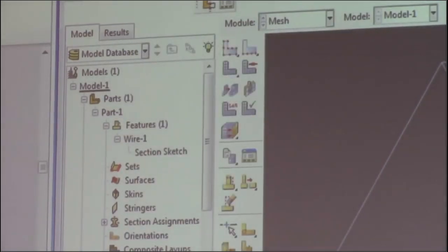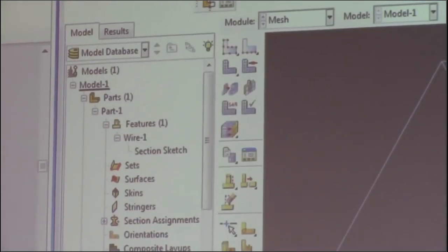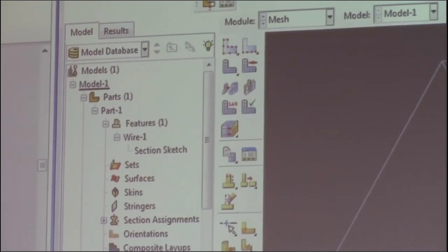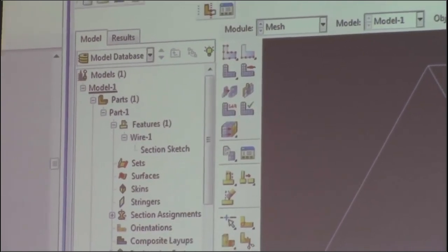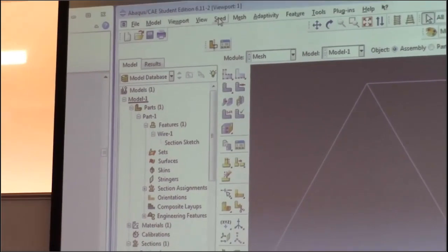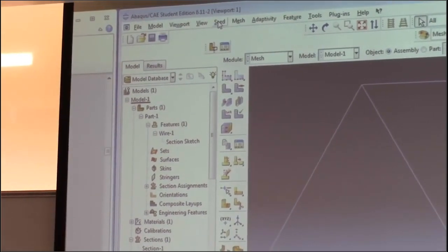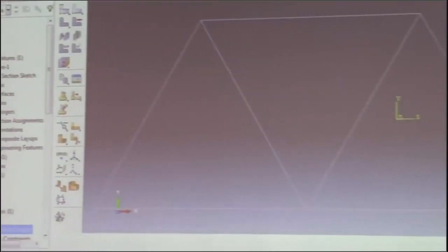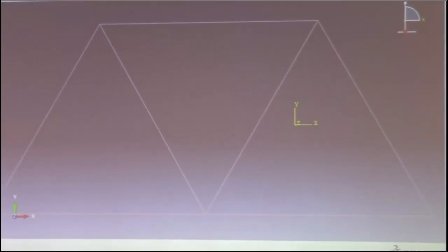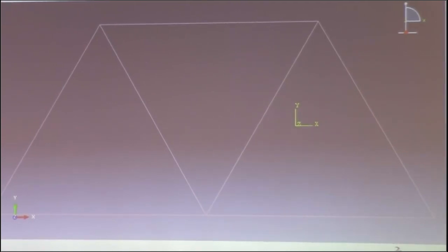So it's treated as a rigid system where the beams can't collapse? This is a truss problem. It's not a beam problem. For a beam problem, you can use as many elements as you want. But for a truss problem, only one element for one truss. Otherwise, if you have a node at the middle of the truss, if you apply compression, your truss will collapse. Yeah.